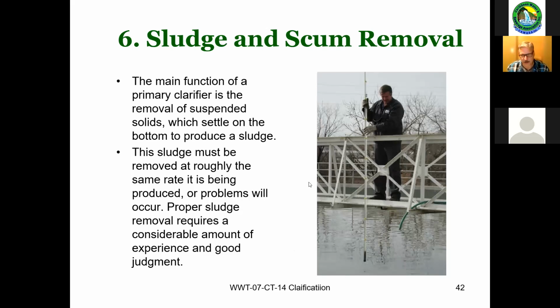For our primary clarifiers, sludge removal is all on a timed operation. So our PLCs tell the pumps to turn on and which valves to open and remove sludge. For operations staff, we've installed a clear piece of pipe on the discharge side of the sludge pump. Part of the operations staff's job is they go down there and take a quick look at the sludge that's flowing through that clear piece of pipe. It's very handy to show a quick glance.